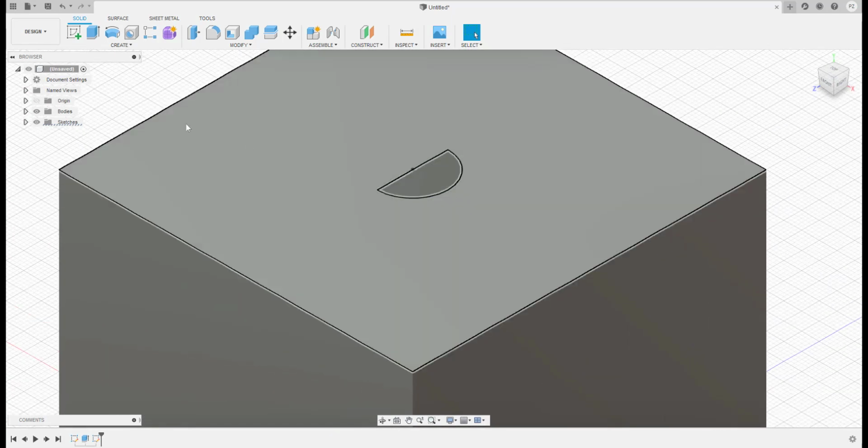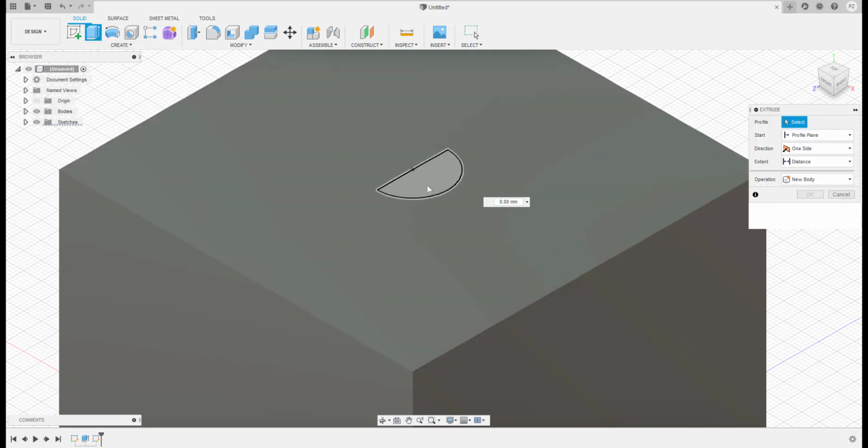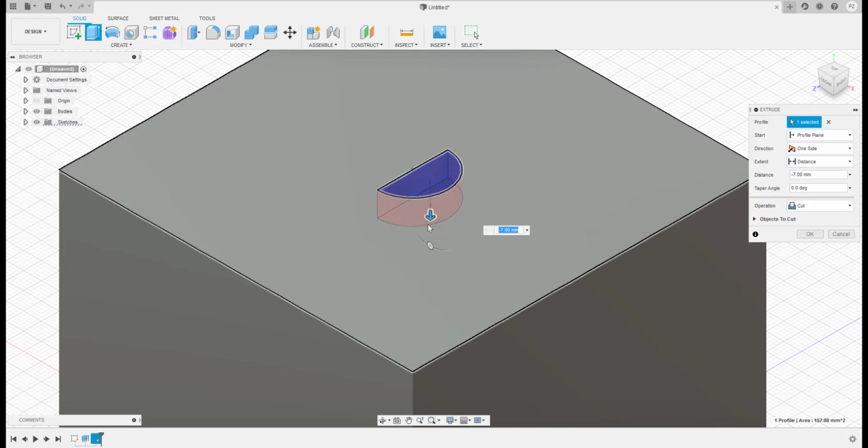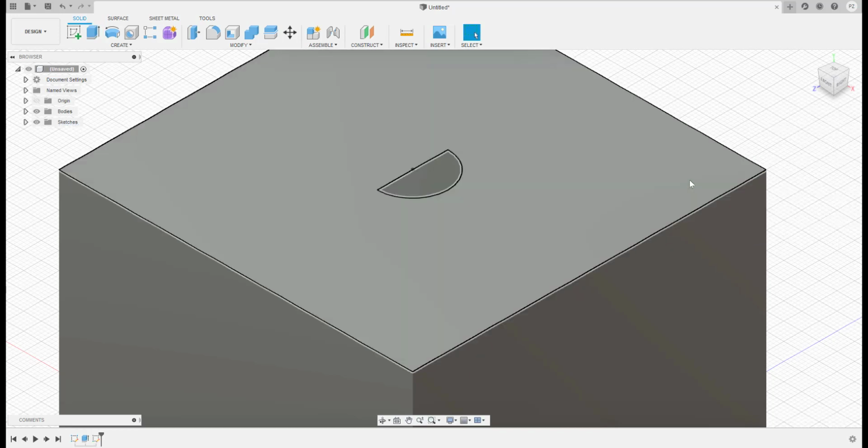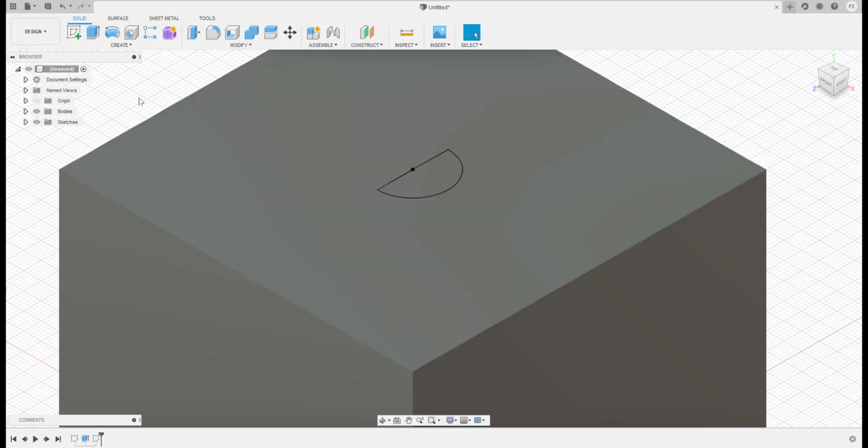And now, instead of extruding this, which we already know we can extrude and go into the shape, that's not what I want. I want it to be round inside. Let me cancel that. Instead of doing that, we're going to do what is known as a revolve. And a revolve is right next to the extrude tool. It's right here. I'm going to click on it.